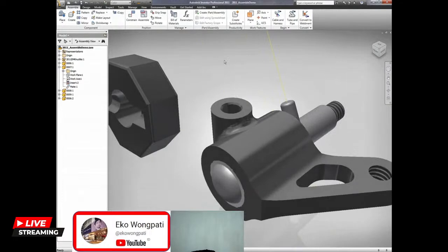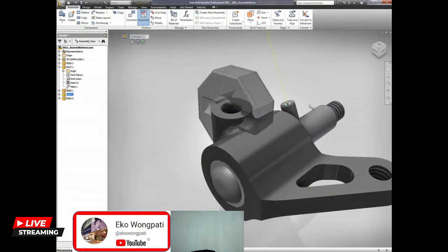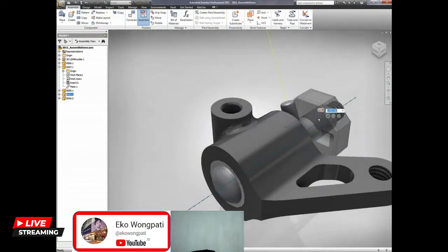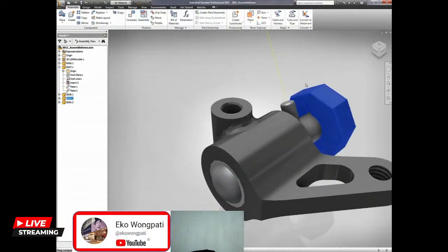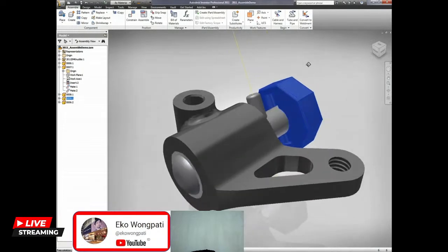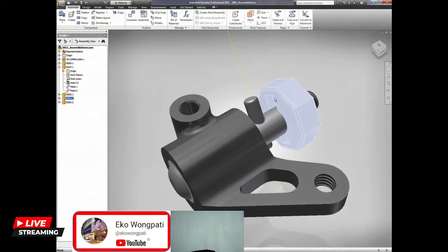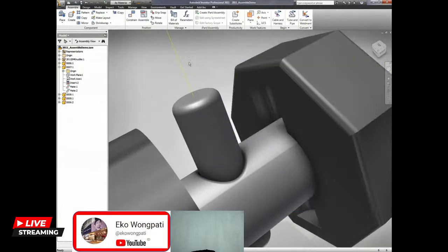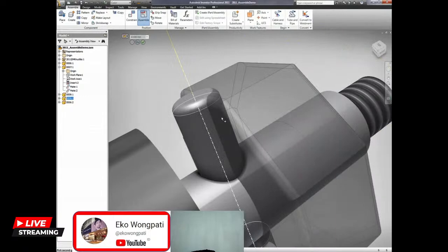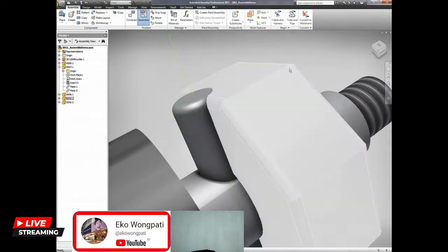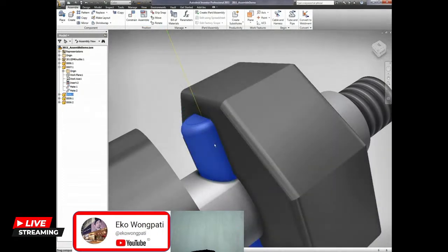So in this example here, I want to go ahead and mate up some different types of geometry, one cylinder to another, and then I also want to go further in depth as far as what types of additional mating considerations I want to make on this component so that things move in relation to each other. Very easily I can bring up that mating condition interface, and on the fly select the face that I want to mate from and select the cylindrical face I want to mate to, and continue to add additional reference mates to this component.